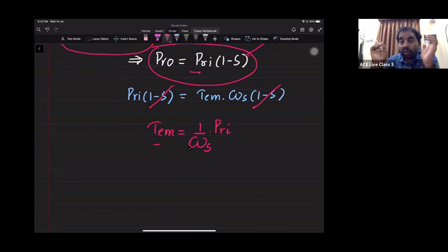Then the active power drawn by the rotor will be less. The starting torque, which depends on that power, will be less. But once the motor starts rotating, as the frequency of the rotor circuit starts decreasing, the inductive nature starts decreasing, the resistance starts dominating, then the power factor will increase, the active power drawn will increase, the torque which depends on that will increase. So that's the reason the running torque is more, right? Is it clear? Confirm me, all of you.